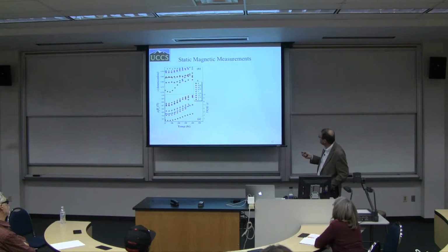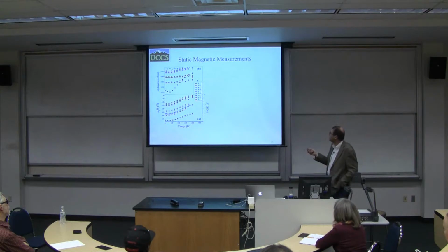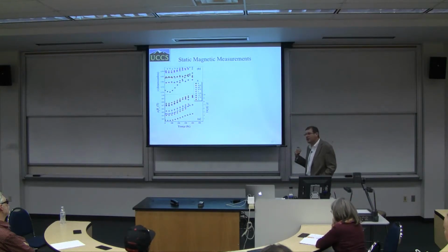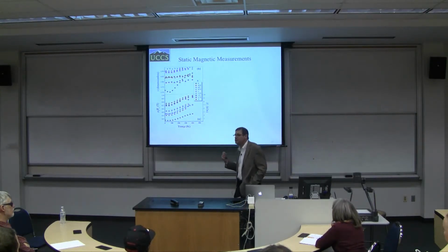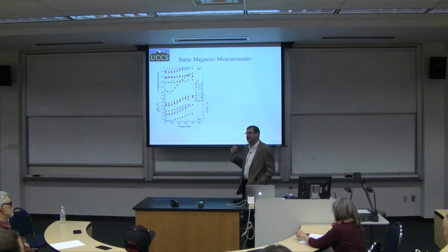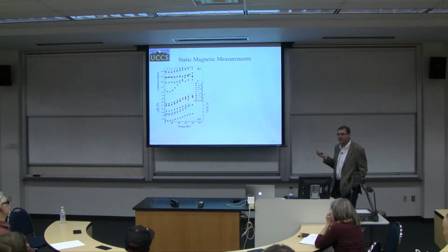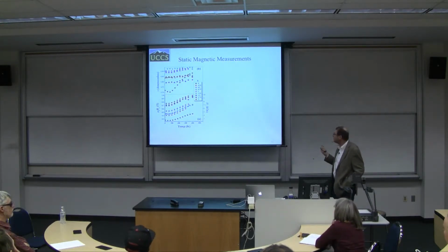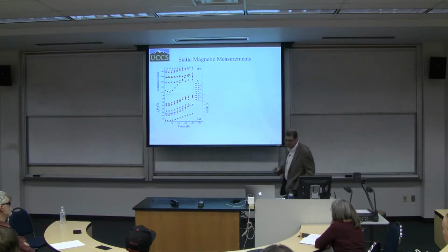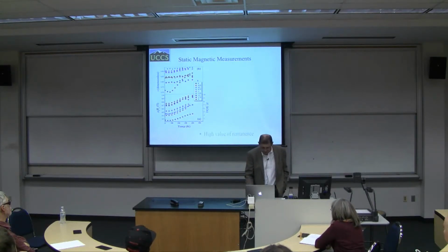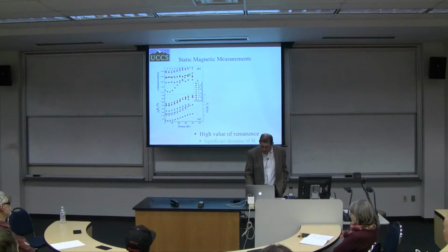And you can see, if I don't take the material which is pure barium hexaferrite, which has significant change, the rest of the materials basically behave in a very predictable fashion, and they are temperature independent. So again, if I have an application which goes to space, because it has to be on a satellite, if I'm changing the temperature, I will not observe any changes in the behavior of my device, and this is something which again is important. So high value of remanence and significant decrease of MS.